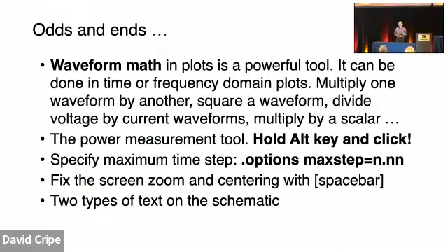Oh, wait a minute. That's something I didn't illustrate, so I was just going to tell you that. I tried a couple of things. You can give those windings a resistance, and in some cases you have to if you just have a voltage source and an inductor. So I gave it 1/10 of an ohm. Then I went back and said, let's make it 1 milliohm. That didn't change anything. I'm going to show later how you can make the time increment smaller. I did that. That didn't change it.